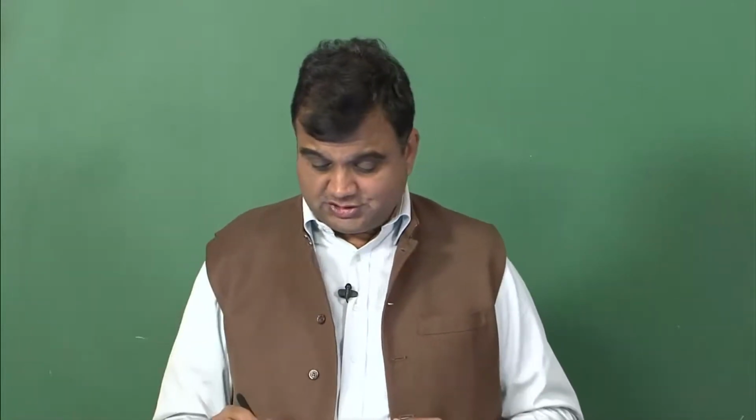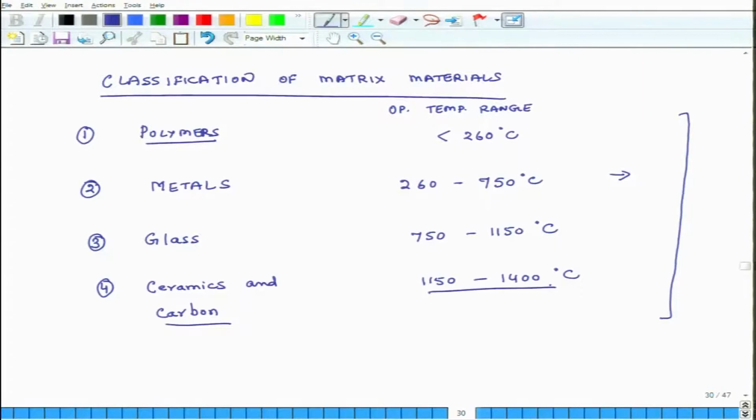So, you have to make sure that if carbon is the matrix material and temperatures are pretty high, then you have to somehow protect it from oxidation. So, you have to coat it in something which is still stable temperature wise and it does not react with carbon and it protects it correctly. So, this is a very important thing to consider.